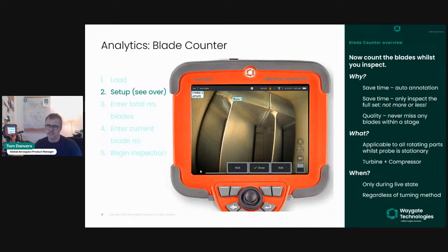So if it has successfully triggered for the number of blades that you've passed through the verification process, it'll say, did you rotate 3 blades? And then you answer yes or no. If you say no, then you're invited to move the probe to another position or change the lighting setup, or just try again, perhaps with different position of your lines, and go through the setup procedure. If it did count correctly during verification, which it did in this video, then you press yes, and then you're into this state where you can start counting.